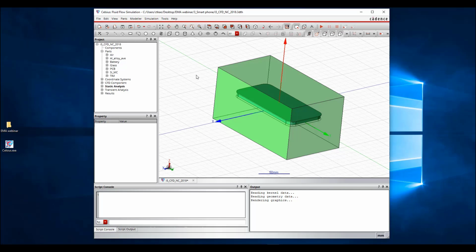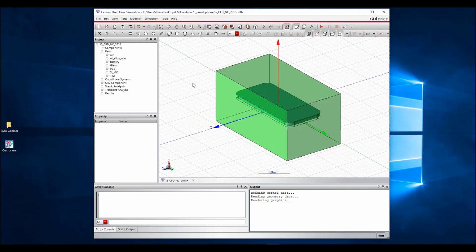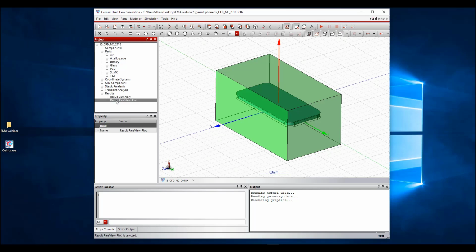So remember the first example, we showed a forced convection. We have a flow coming into the flow domain, maybe from the fan or other apparatus. But here for the smartphone, basically we cannot have a fan, but we need to rely on the natural convection of the air. So after we specify all the things, including material properties, then we can carry on this CFD simulation. So I'll omit the running and show you some results like before.